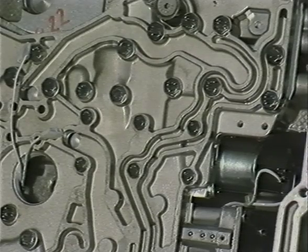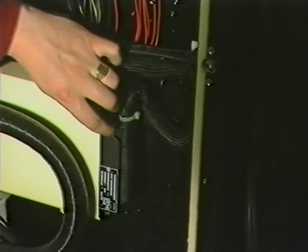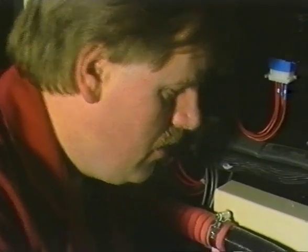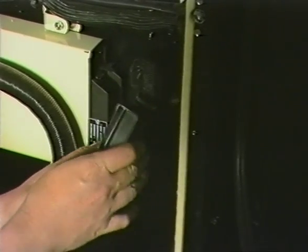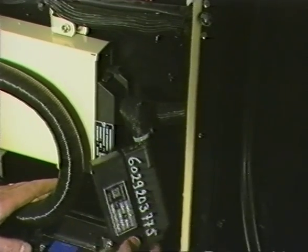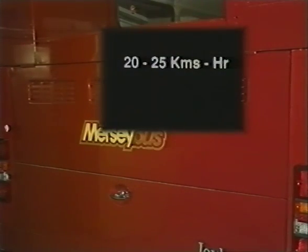In instances of vehicle breakdown, when the fault is within the control panel, an emergency link can be installed which bypasses the control system and allows direct selection of second and reverse gear. It should be noted that if it's necessary to tow the vehicle, there is a speed limit of 20 to 25 kilometers per hour, and the towing period should not exceed 2 hours.